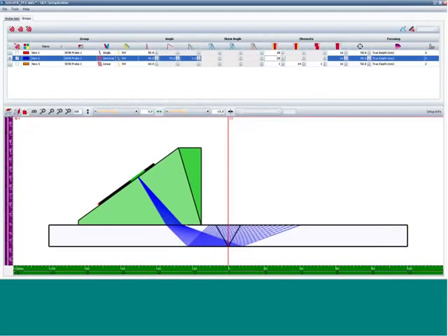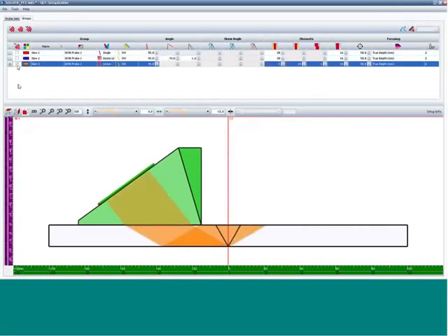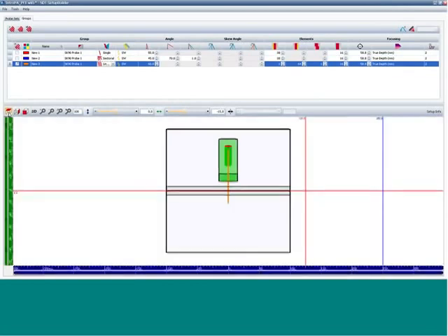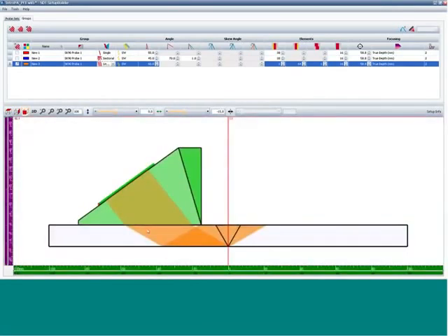Another type of group is the linear scan group. In this case, we select linear here, and it's all going to be at one angle, 60 degree. A perfect inspection for a 30-degree weld bevel is a 60-degree incident angle. So we're simply replacing mechanical movement with electrical movement of the beam.